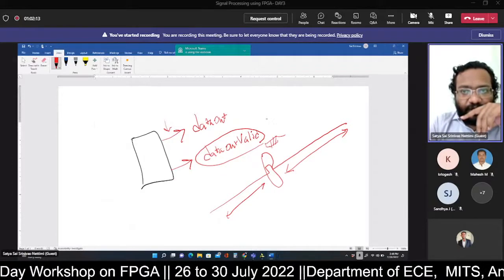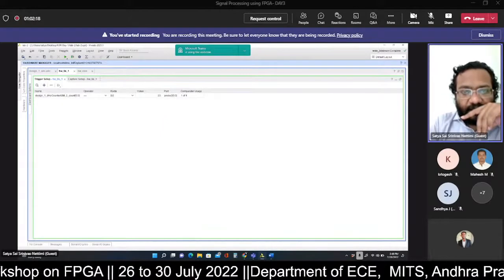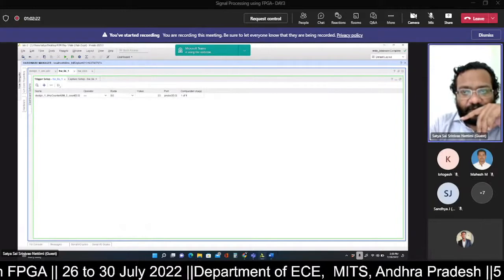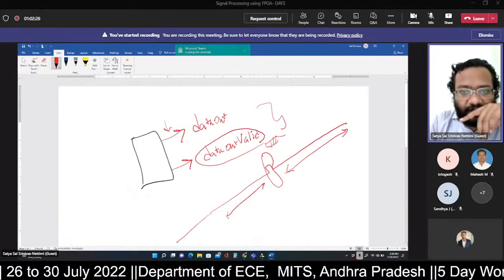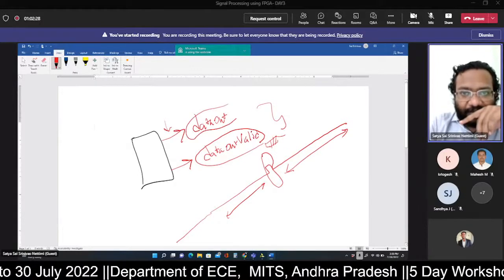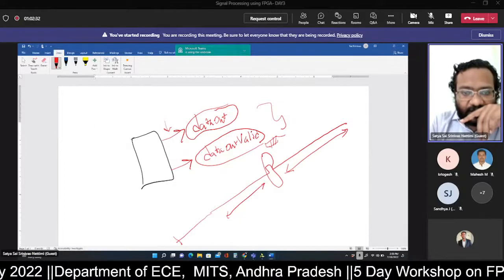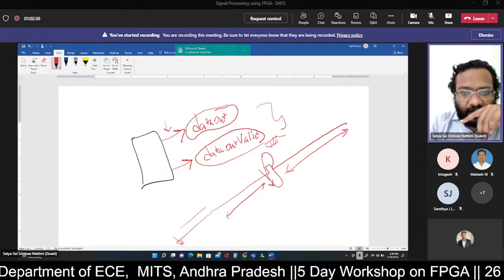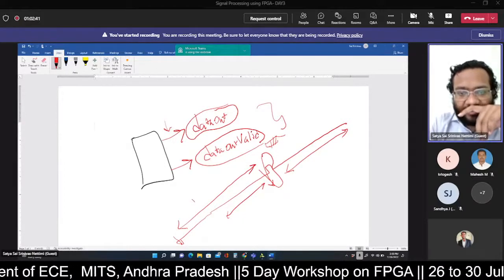So if you don't give a trigger setup like this, where only whenever data valid is equal to 1 you capture the data, then the trigger setup will capture whatever data is coming on data output. For example, it has started capturing data from here. From here to here, the data capturing will depend on the total configured memory depth size.